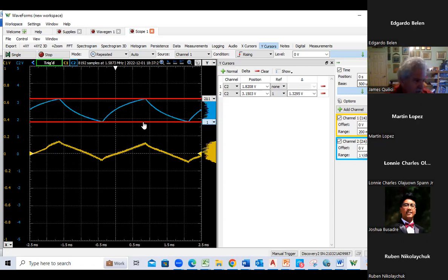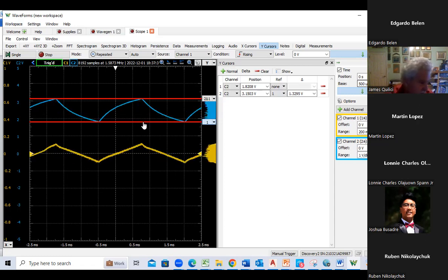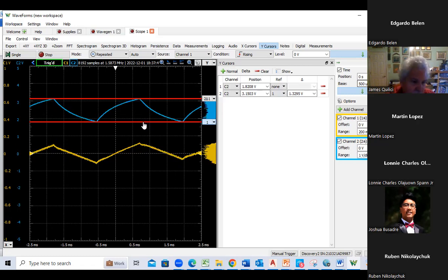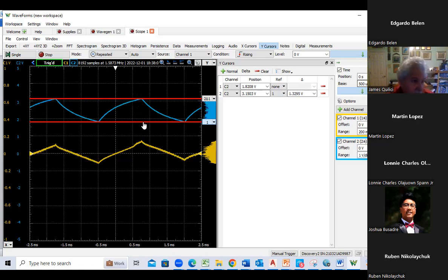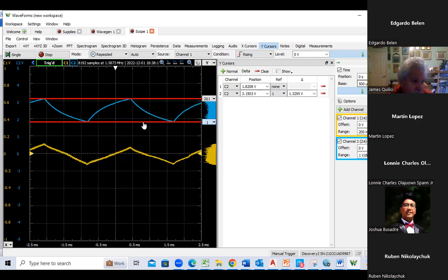Okay, so that's basically the testing you're going to do. So what I want you to do then, again, just to repeat myself, is at the end of your report, you should have the final circuit that you built with all the components. If it's different than what you simulated, maybe comment on why it's different. Maybe like you had to still change RE to increase the gain to get it within your spec. But the specs have a value for minimum peak to peak voltage. Comment and show an oscilloscope display that you met that. And then comment on the gain, that you met your gain spec.